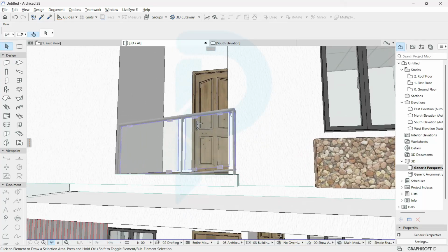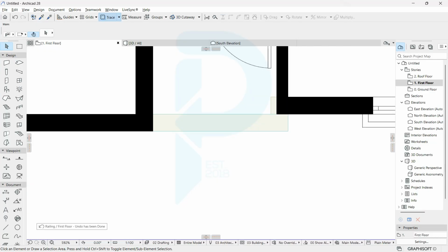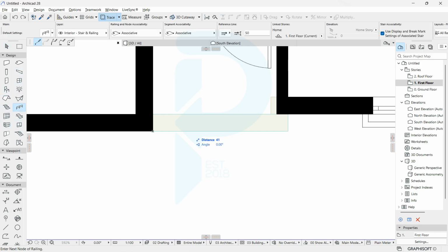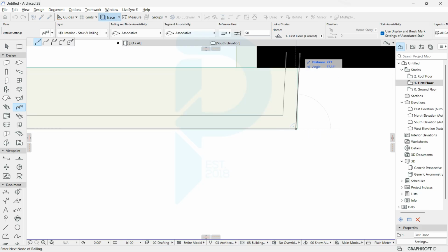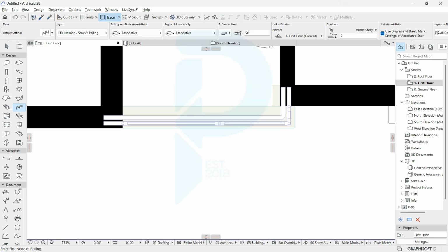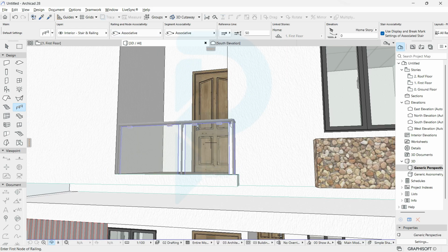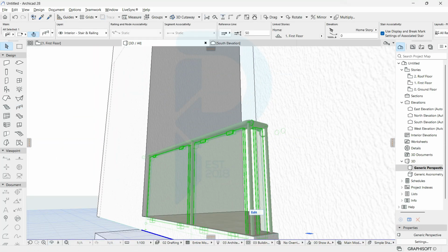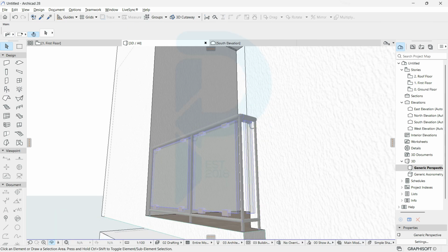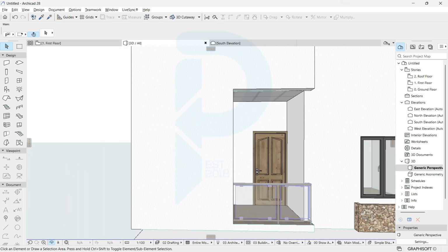Yeah, there's an error in the placing. I have to do that again. Where's my railing? Rail tool. Keep forgetting what that looks like. I don't want to have an error there. I think it's trying to read the slab, it's trying to follow the path of the slab, so that's why it's giving me that error. And then I click on it. I just take it up by 150, because the slab is positioned in such a way that it's taking a portion of the story height there.